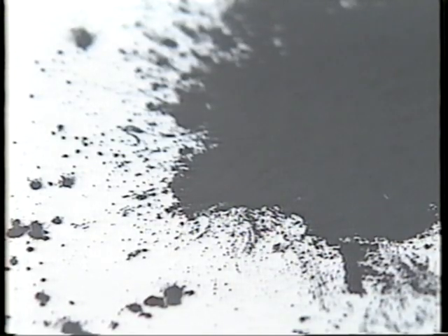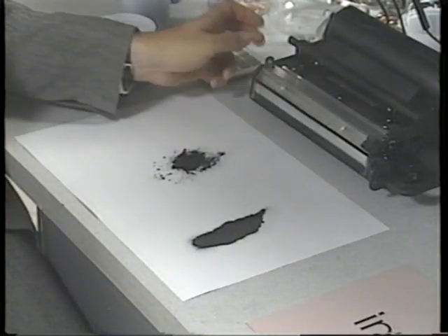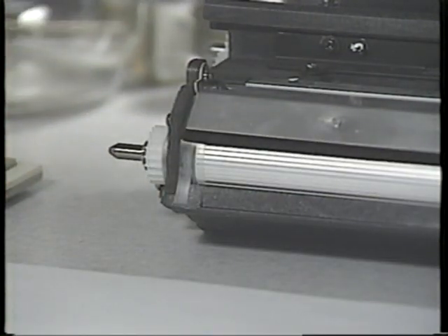It's made from resin combined with carbon or colored pigment. Toner isn't magnetic, but it will respond to an electrical field. Inside the development unit, toner and carrier are mixed together, and the toner gets an electrical charge that's opposite the charge of the latent image. Then a special roller brushes some toner over the photoconductor. Since opposite charges attract, the latent image attracts toner particles and becomes coated with black or whatever color toner you're using. The latent image becomes a visible image.